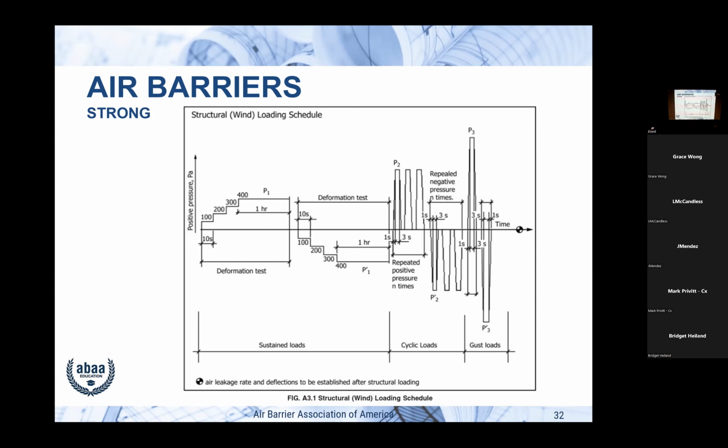Okay. What people don't understand, ASTM E2357 is an excellent test. This is what you saw. It's designed for buildings that are 3 stories and less, and that covers 80% of the buildings in the United States. For 20% of the buildings in the United States, even if they're 3 stories and less, it's not strong enough. If you're over 3 stories, you've got to go to your wind engineer. Depending on where you are, you may still be okay, but it could be completely different. And the reason why we say 3 stories and less is why.